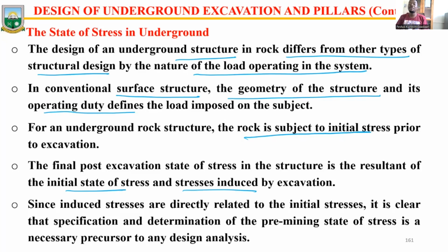And then when you have caused your disturbances, if you want to compute the stresses this time around, it is that initial stress that existed before your disturbance plus the stresses that are being induced by your activity. So these two things come together to give us the post-excavation stress.